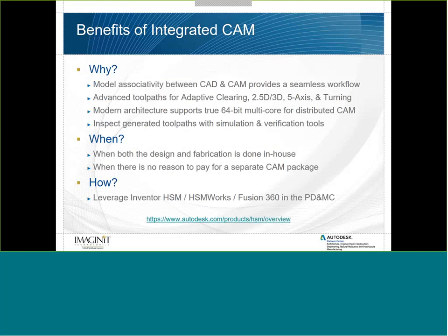Of course, taking advantage of advanced tool paths, in particular adaptive clearing, to very quickly remove material in roughing operations. But then also having the 2.5D and 3D tools, 5-axis tools, turning tools, even cutting tools for water jet, laser, and plasma.